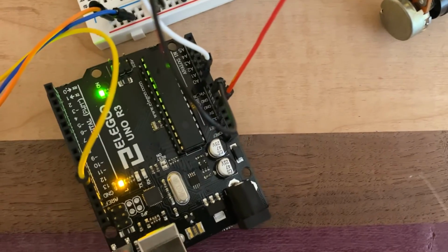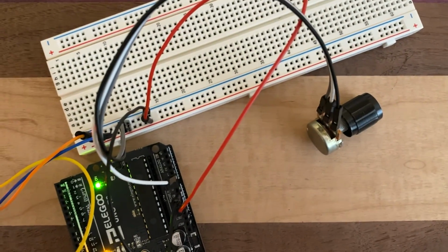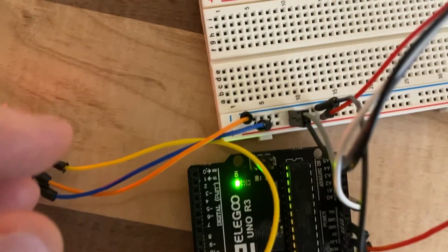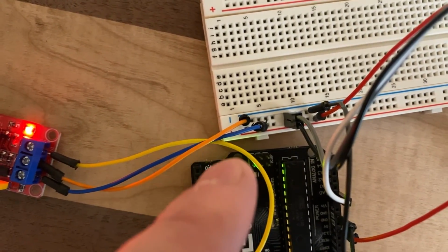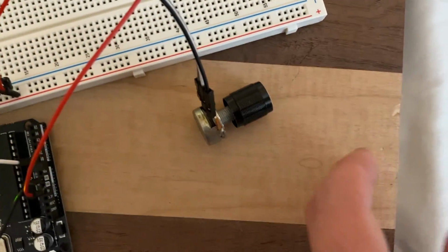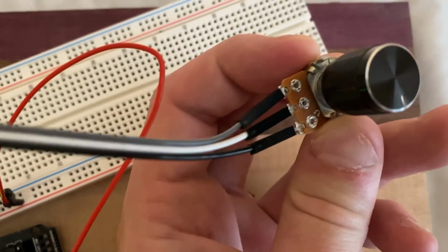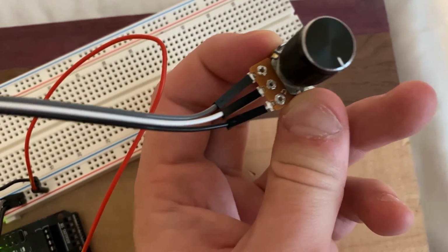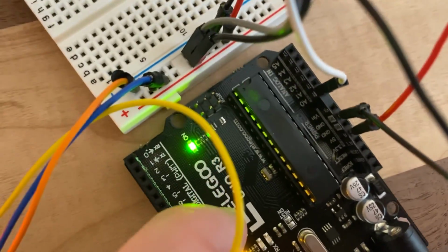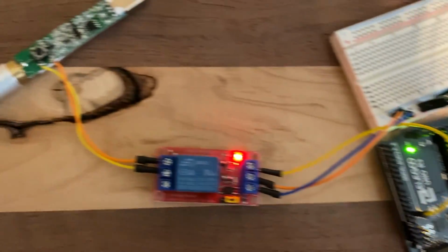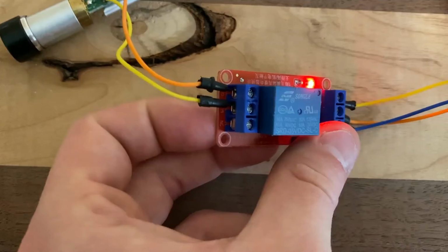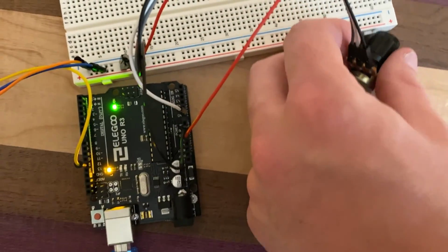And then I have my ground and my 5-volt plugs actually plugged into right here on the relay. Now these sidebars, they go vertical. You can see I have my ground and my positive plugged into the relay here, and I have the ground and positive plugged into the left and right ports on my potentiometer. And this middle plug right here, this white one, is actually plugged into my A0 analog in. And then I have a green laser that's just plugged into the relay that gets activated whenever this potentiometer gets turned.